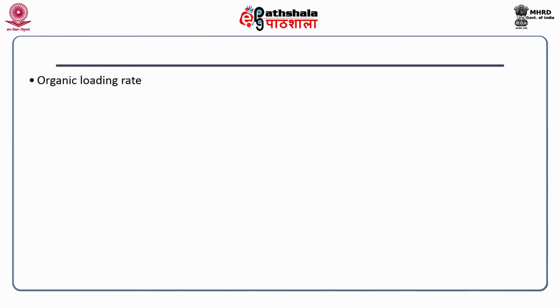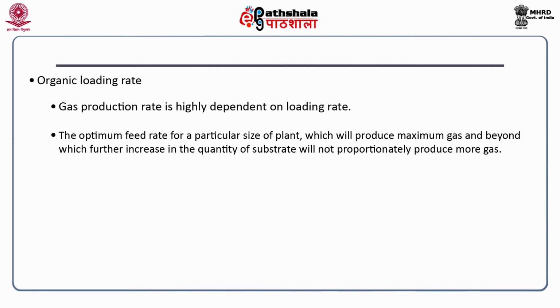Now, the organic loading rate. The gas production rate is highly dependent on this organic loading rate. There is an optimum feed rate for a particular size of plant which will produce maximum gas, beyond which further increase in the quantity of substrate does not proportionately produce more gas.